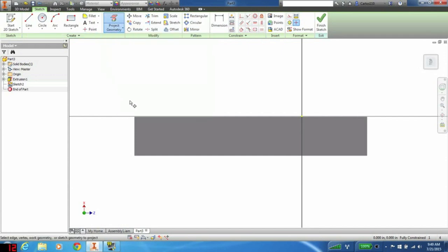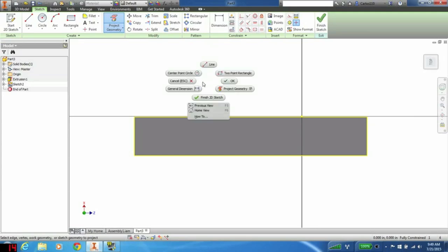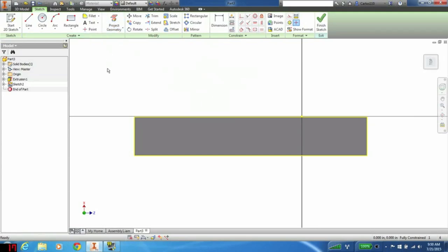Now this will take the instance where the object that we now select overlaps with the sketch plane that we are using. So this will give us exactly what we see in front of us. So in order to get this rectangle, we're going to hover over until we have the entire face selected, not just one of the edges. I'm going to click, and now you can see as I move my mouse away, it's yellow around the outside. Those yellow lines we can now use to reference 4 dimensions. So I'm going to right click and cancel to exit out of the tool.